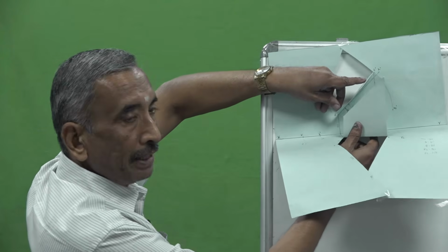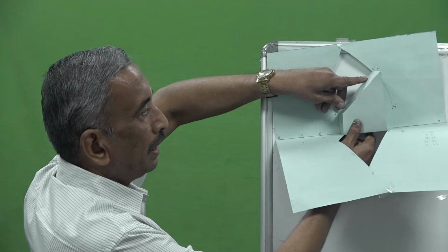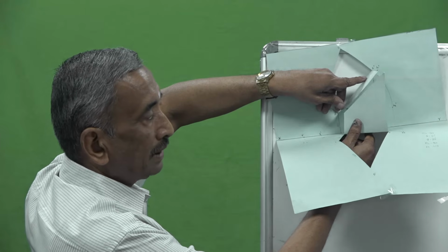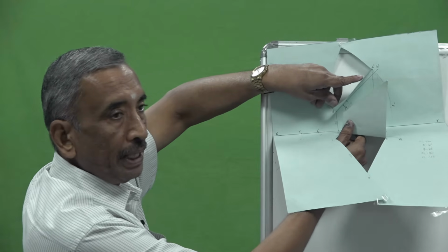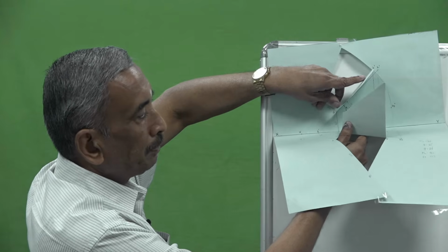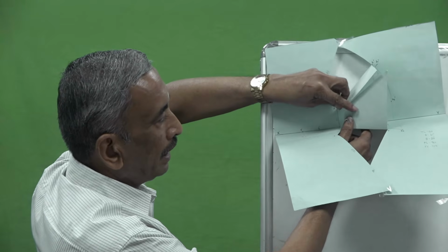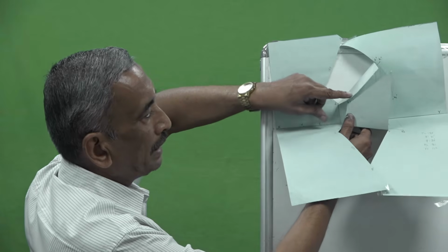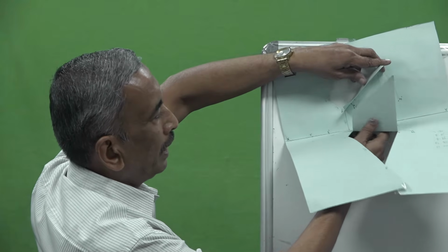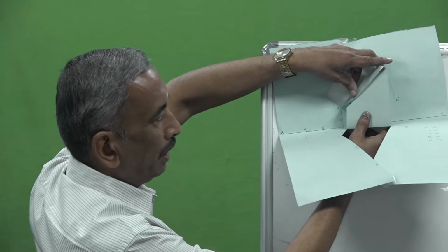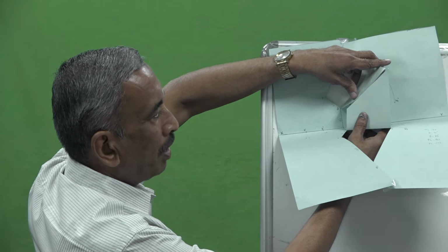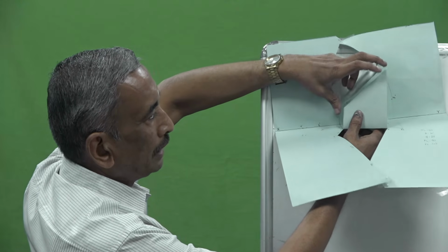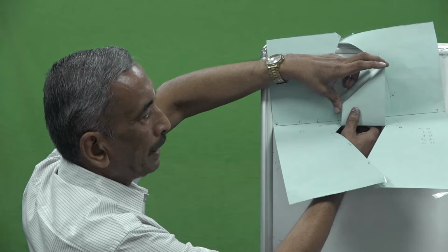So, model making is very important, and see that you are understanding the concept of true length, the true angle with respect to HP, that is this angle, and the true angle the line makes with respect to VP, that is angle phi. So, kindly make this model, and once you make this model you can join these two. So, this represents the line inclined to both HP and VP.